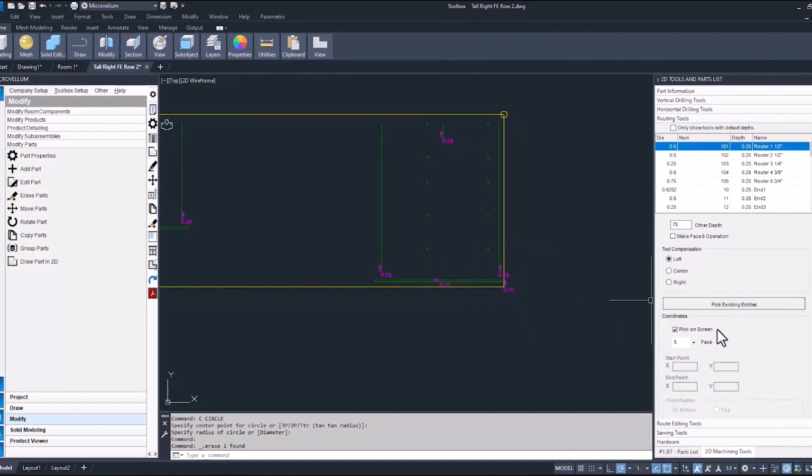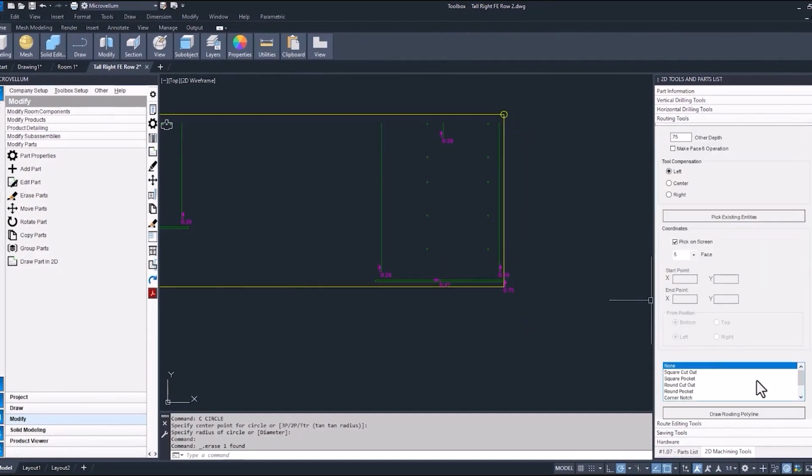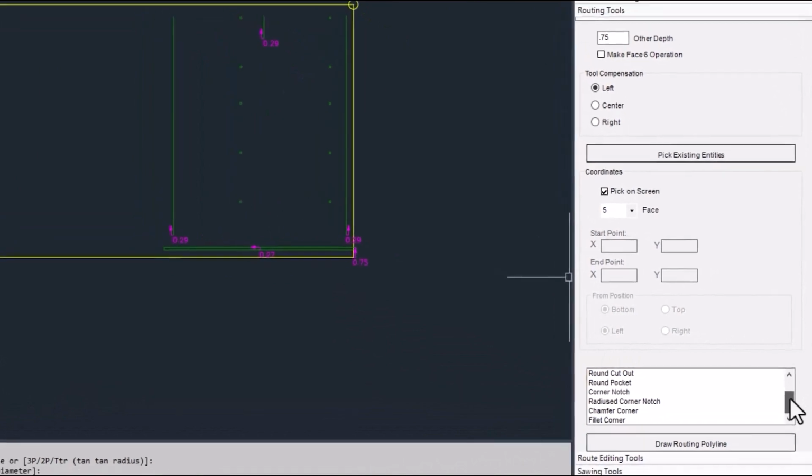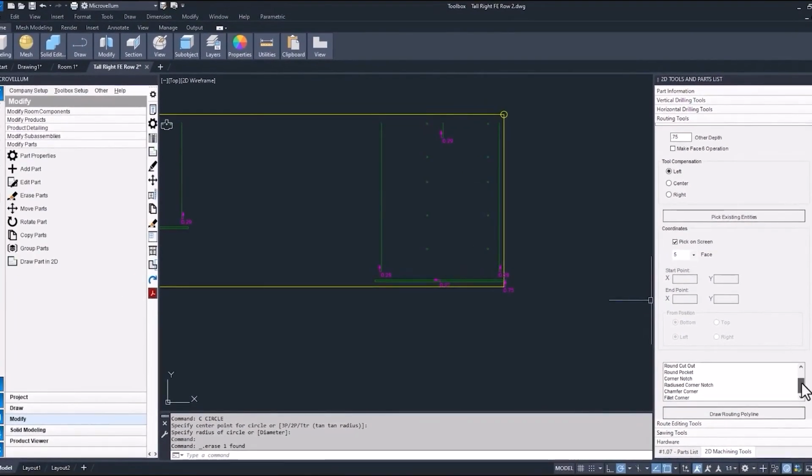We're going to scroll down on the screen, and the bottom of this palette gives you a list of what we call machine tokens. So these tokens can be applied directly to the part, and they're coming in with some properties from Toolbox, letting it know whether it needs to be a round cutout, square, pocketed or not. Now when you pocket a cutout, it means that it's actually removing all the material inside of that cutout. What I like to say is just creating sawdust with that hole or square part that it's removing.